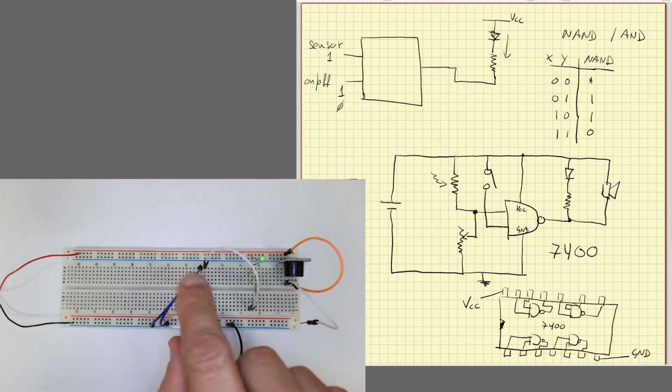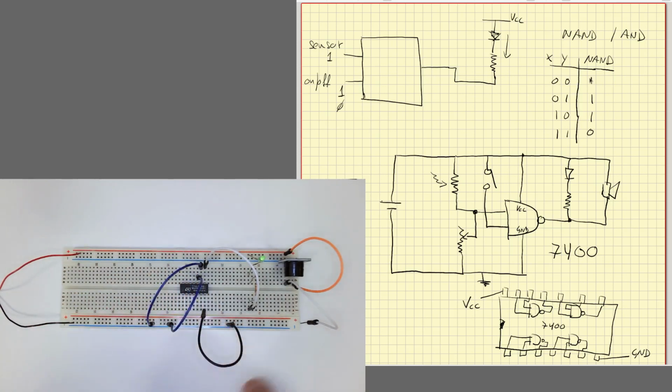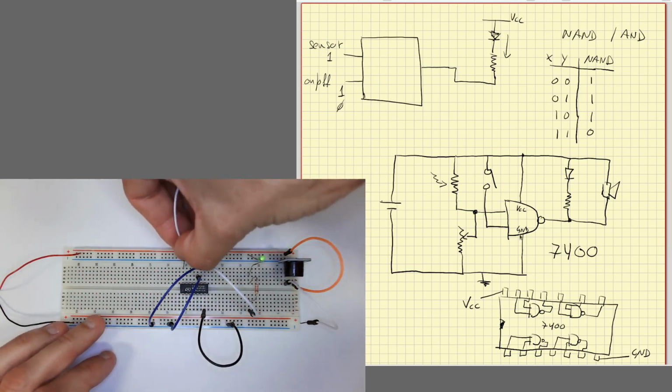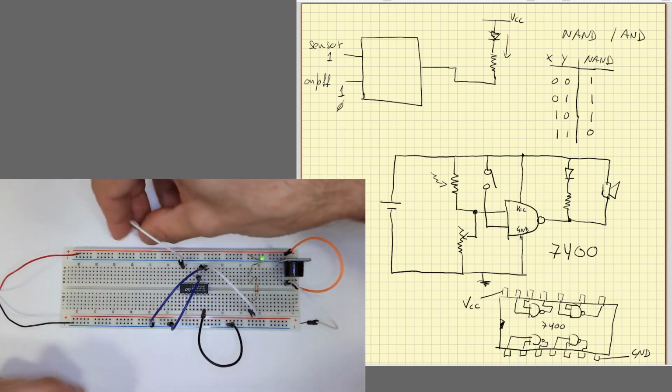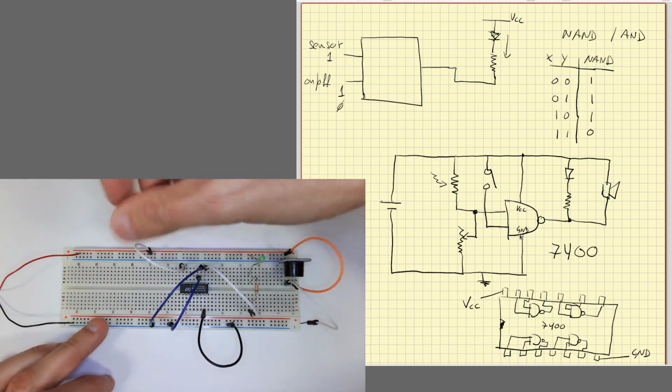It's not high actually, because if the output is high, the LED should not light, but the problem is that I have not connected the power supply. So my circuit is still not working. I need to put energy inside the circuit. So I will connect the power supply, this to the positive terminal.